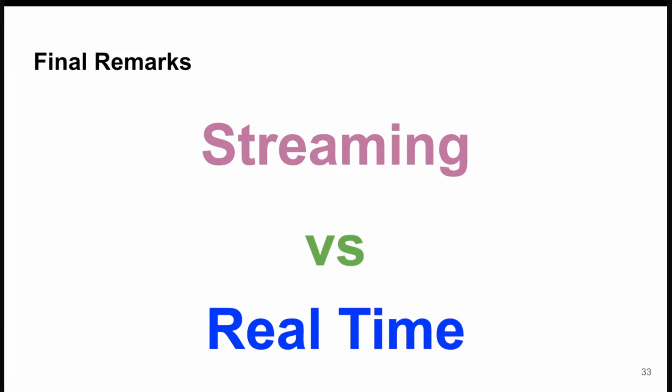Therefore, it doesn't chop up the audio, or generate a broken output, because it keeps a state that remembers the previous audio inputs it had. When we execute as a real-time system, we put a cap on latency and jitter, which means we usually need to run this algorithm several times per second in order to keep up with incoming data. If we don't keep up, we are going to break the deadlines that we set, and therefore the algorithm is not going to run in real time.